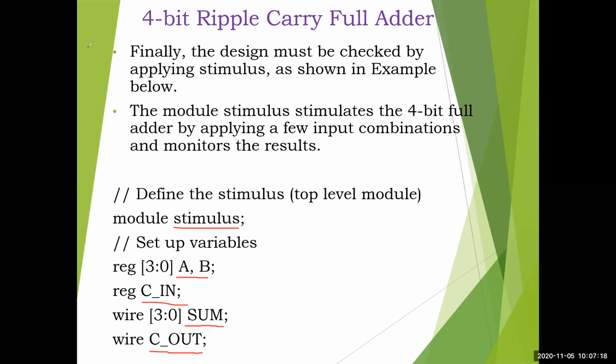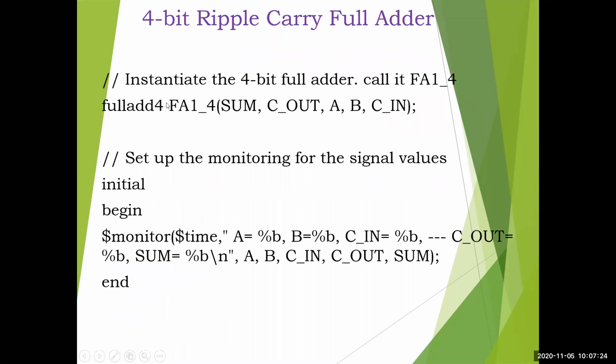Okay, so we'll continue. Next we'll just call the design. We will call the 4-bit full adder, because this 4-bit full adder again will call the 1-bit full adder, right? We are not doing one 4-bit full adder here; we are calling full add 4 now. Its name is full add 4, and we have given some new instance name. It is just for reference when we are checking, so it is not doing much in the design.